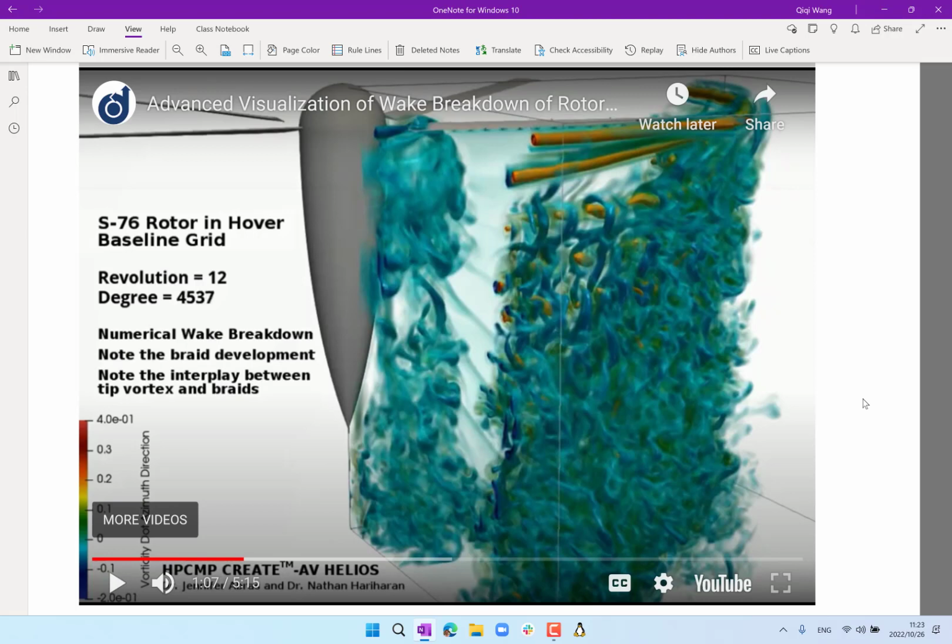And this is the primary mechanism of what's generating turbulence in three-dimensional flow. And this is actually why turbulence doesn't exist, at least in the classical sense of turbulence, in two-dimensional aerodynamics. But in three-dimensional aerodynamics, as soon as you have multiple vortices interacting with each other, you get turbulence pretty quickly, right? And that's what's happening over here.